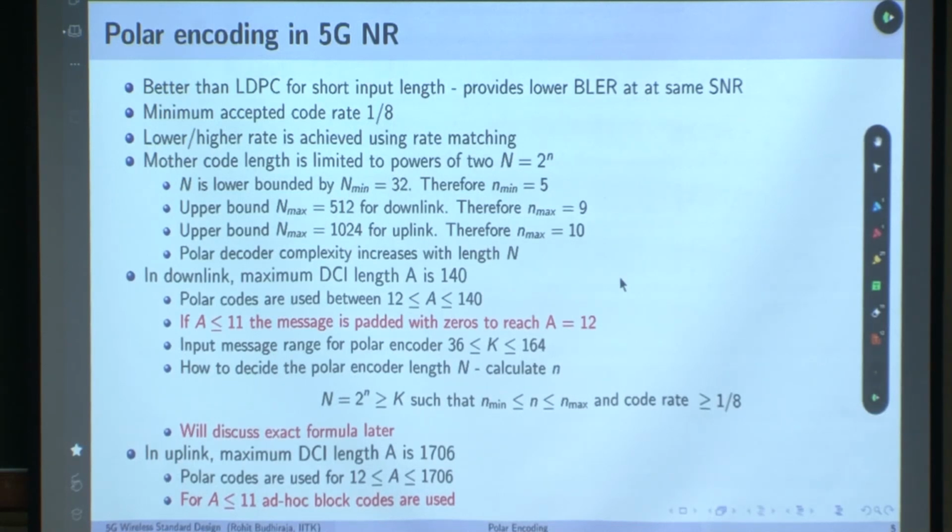Then to summarize, the key ideas here are that the polar encoder is designed to create n virtual channels. Out of these n virtual channels, those k channels which have the maximum reliability are given to the message bits. The rest of the channels are given to the other parity bits, so that you get your message bits without any corruption in the given SNR range where this polar encoder is going to work.